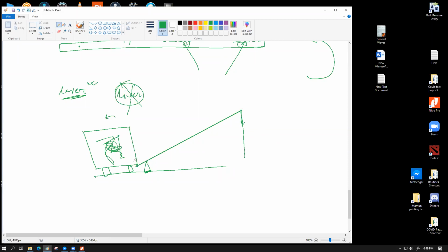But when this bar becomes horizontal, you can see that this end moves by a huge distance, whereas the other end moves up by a very small amount. So we are going to have a huge advantage of force, because we are basically rotating this rod about this point.